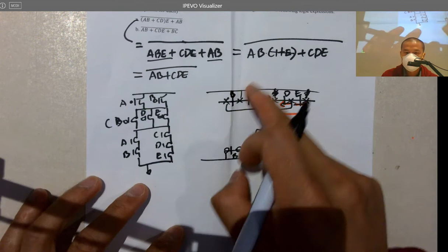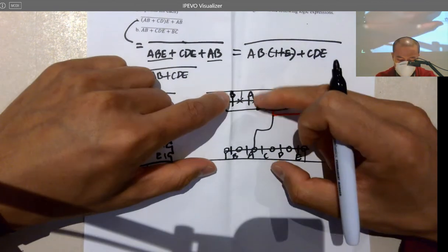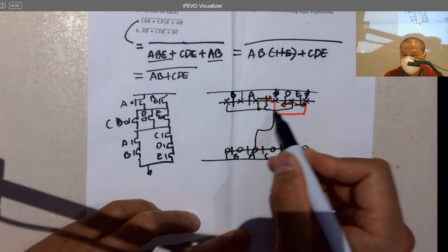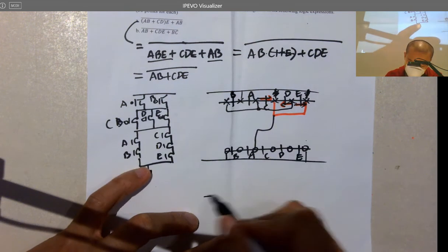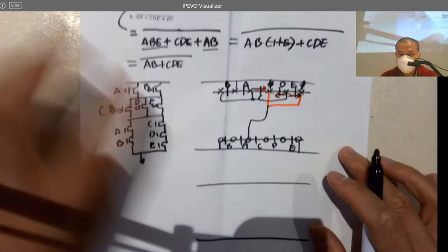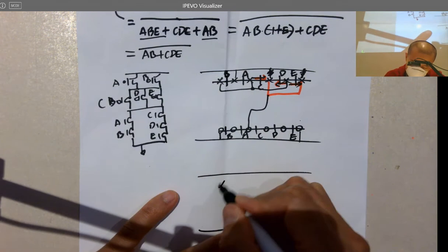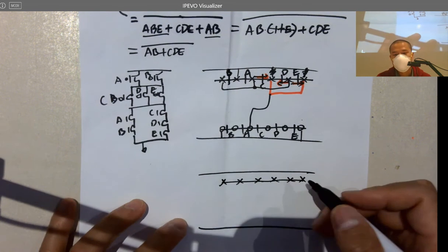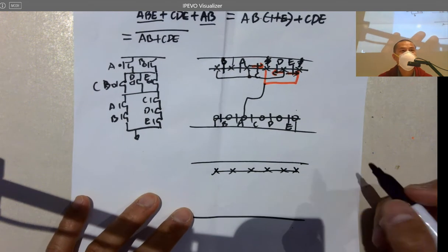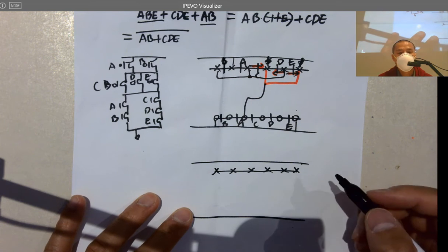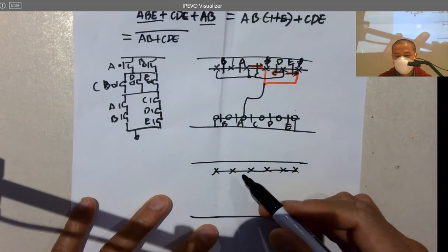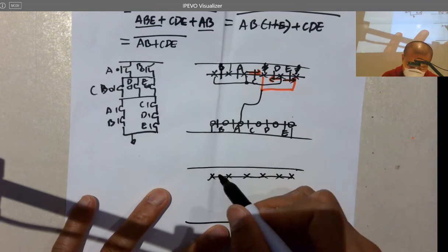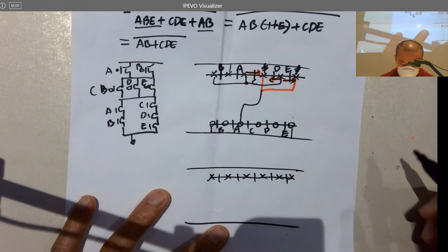So now let's look at this one, see if there's a better option. If we do the parallel from the top, we can get rid of this intersection between these two traces. Just the top part, trying to optimize it. 1, 2, 3, 4, 5, 6. So now you'll see the benefit of doing stick diagrams, right? Before you lay it out in electrical VLSI, you can actually pre-design it before you do anything there to optimize the traces. 1, 2, 3, 4, 5.